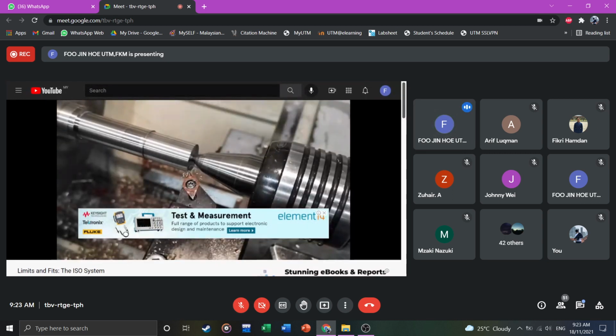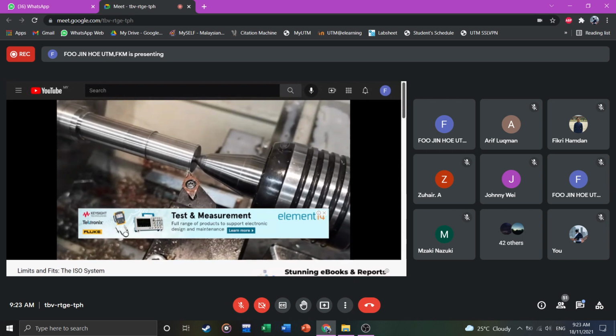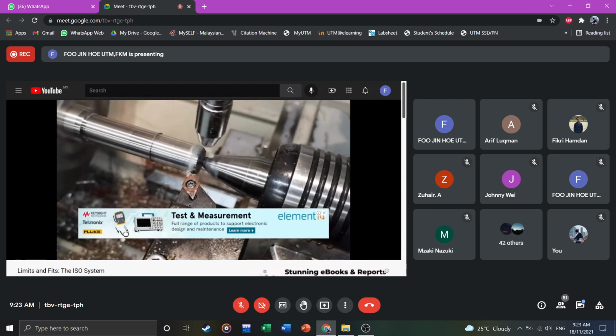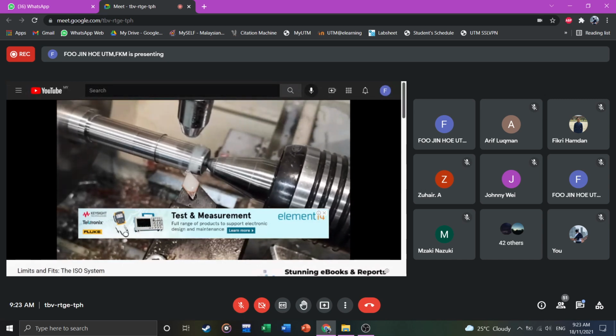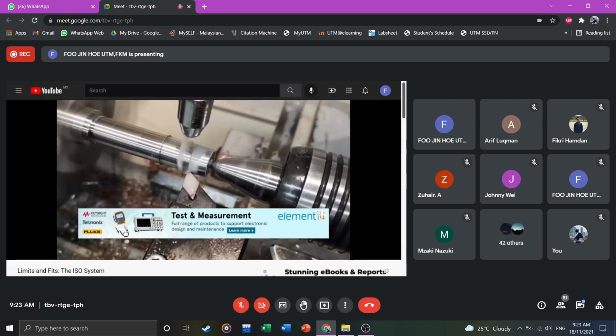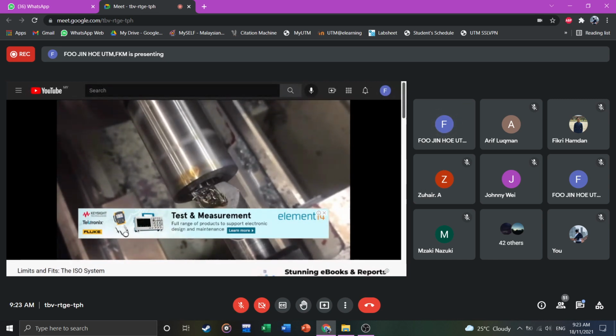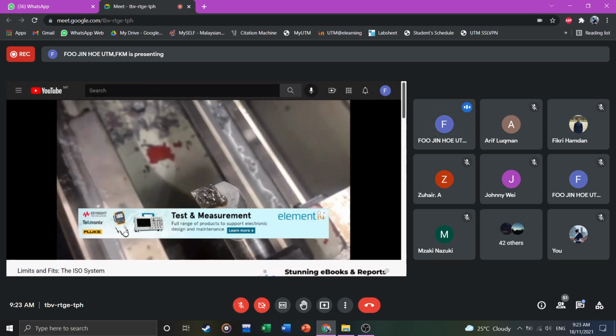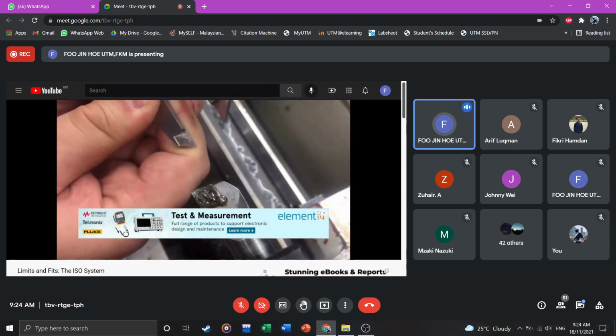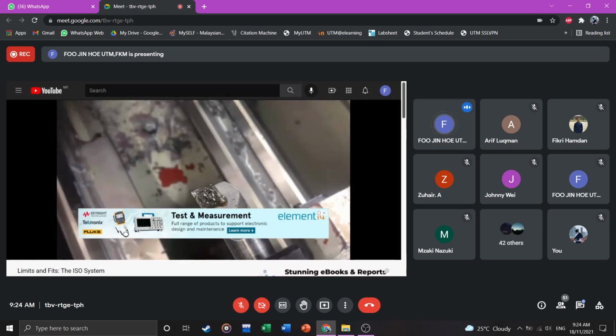Before we get any further, I should mention that I'll be talking about shafts and pins fitting in holes. But per ISO 286, this system can be used for internal and external features of size. You'll sometimes see it used for keys fitting in keyways, for example. How things fit together is determined by how much free space there is between the two parts. If there's lots, there will be lots of space for the parts to move. If there's only a little, there'll be a lot less space. Finally, if there's no space, the part won't be able to move.